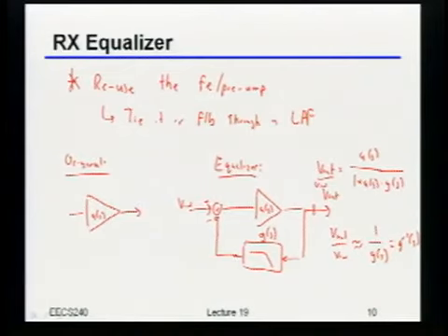So I'm getting exactly this equalizer behavior, where I've reduced the gain at DC, and at high frequencies I'm getting more of that gain. In other words, I'm implementing the inverse of whatever's in that feedback network. So now, just to make sure this is clear, if you could put anything you wanted into this feedback network, what would you put?